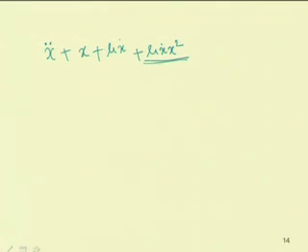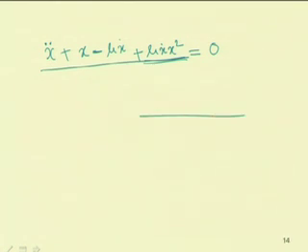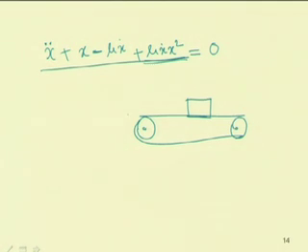Here you can put a negative damping mu. Due to the presence of negative damping, this is a self excited system. In the self excited system, due to the generation of energy by this damping force, the system will behave in a particular way. So, one can get a periodic response in the self excited type of motion. For example, this type of system can be obtained by considering a conveyor belt system carrying blocks or some material. When the block is moving on this, the force can be modeled as a Duffing type of equation.